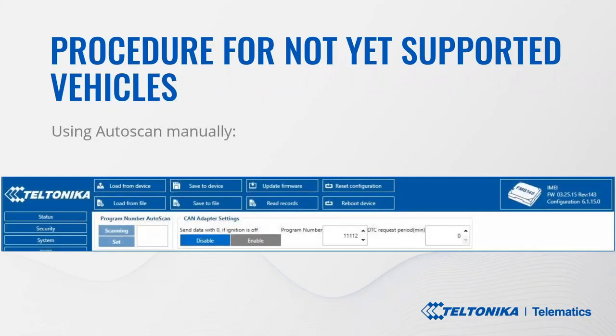Another way to proceed with auto scan is simply connecting to the configurator. After the connection is done successfully, you can launch the configurator and navigate to the CAN adapter tab. Of course, before clicking the scan button, make sure that the ignition is on and the ignition source is configured to digital input 1 or power voltage.